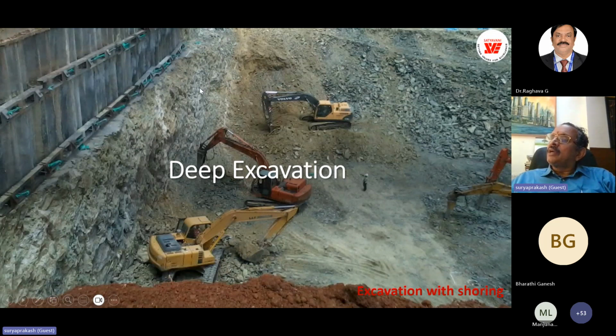So it is very difficult to control the soft disintegrated rock while maintaining the profile as per the design. This is a practical problem. But still, they went ahead against our DBR, and then there was a failure of this pile. These wedge anchors highly depend on these nails, and these nails depend on the wedge actually.